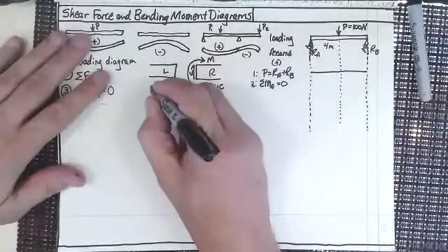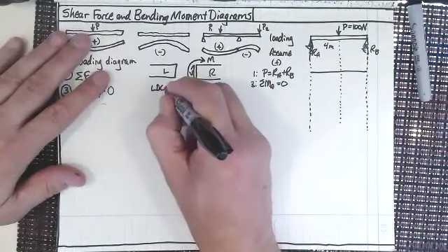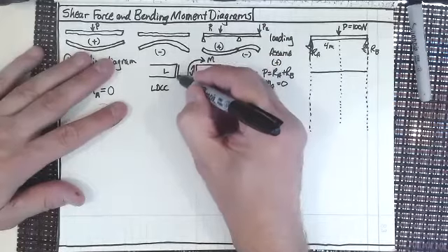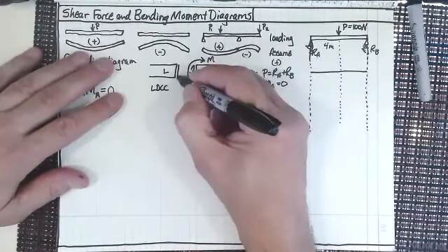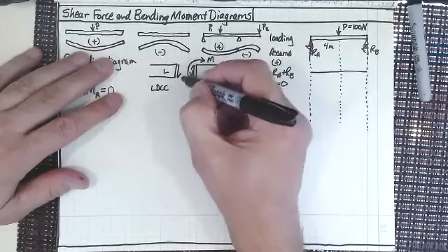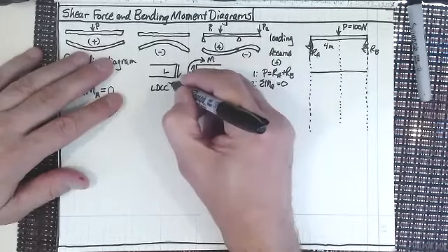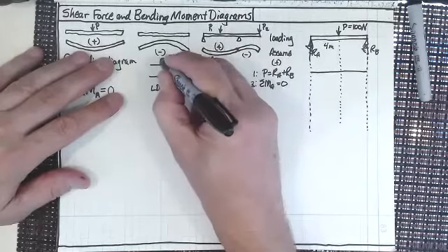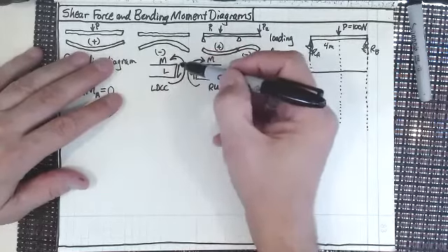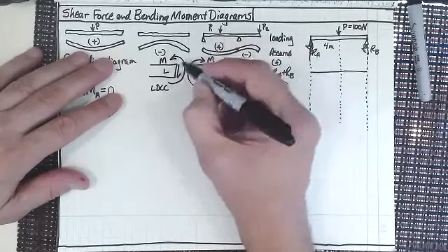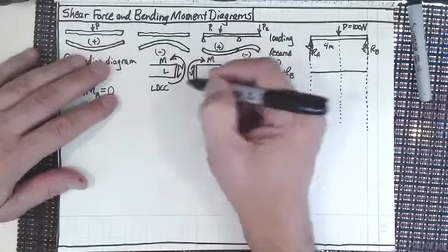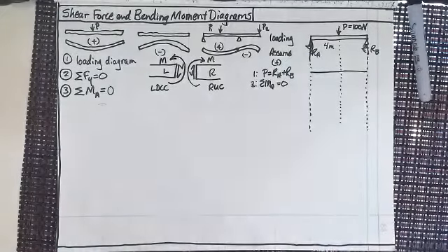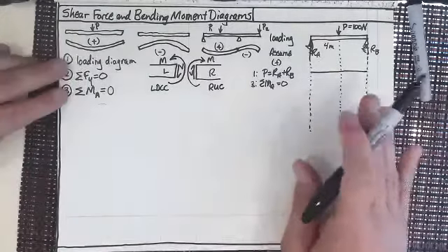I don't have to remember the other one however you pronounce that, because I remembered RUCK, right? So obviously the left side is down and then counterclockwise. And that way these two opposing moments and forces offset each other, right? Because this is V going down. And then we just sum them. Whatever else we've got on the right-hand side, we sum that all together.